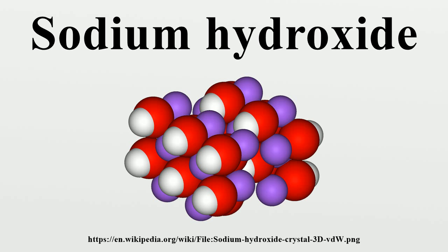The sodium hydroxide-based detergent includes surfactants, rust inhibitors and defoamers. A parts washer heats water and the detergent in a closed cabinet and then sprays the heated sodium hydroxide and hot water at pressure against dirty parts for degreasing applications. Sodium hydroxide used in this manner replaced many solvent-based systems in the early 1990s when trichloroethane was outlawed by the Montreal Protocol. Water and sodium hydroxide detergent-based parts washes are considered to be an environmental improvement over the solvent-based cleaning methods.